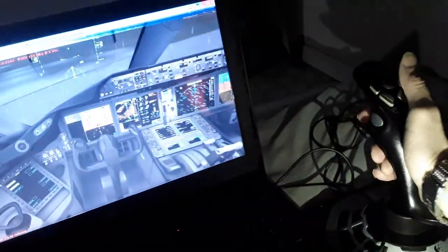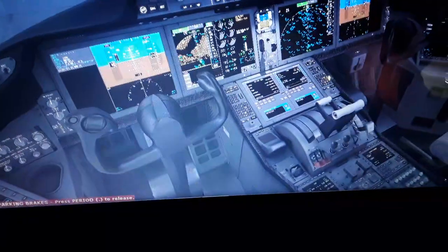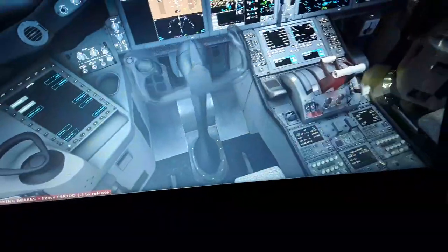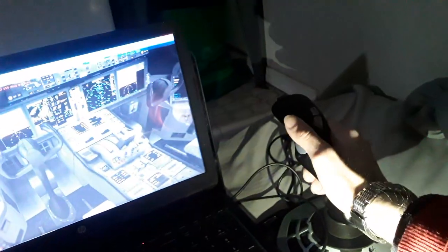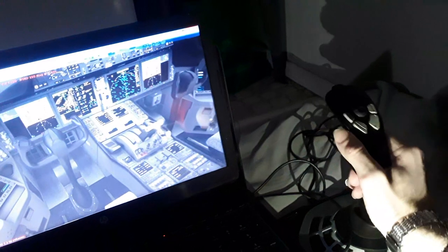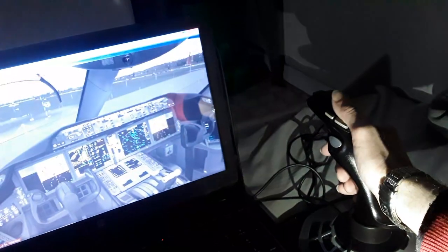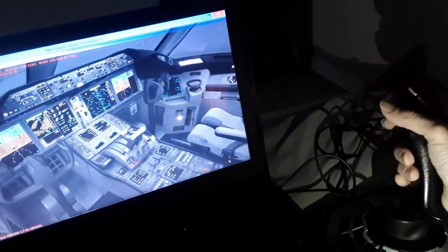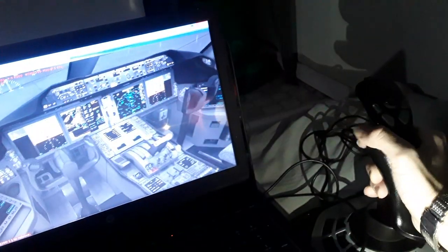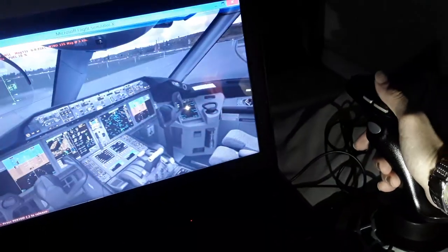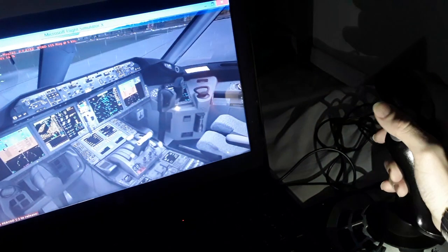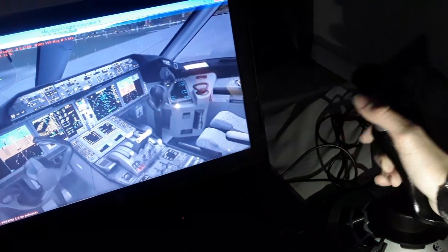So he's using the rudder pedals like this to make yaw turns, all the vertical rudder. So it's quite simple. You can use all controls together or only one of them, only ailerons or elevator or rudder pedals. So you can see both sides are interconnected, the captain and the first officer, so that they move independently from each other. Unlike in the Airbus, you have the side stick priority from each side. So unless you have a failure, they will move together in flight.